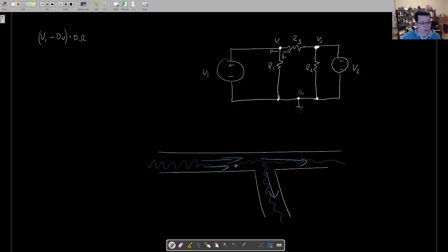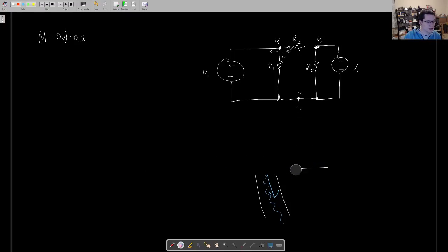And at the same time, everything you've put into your pipe must come out of your pipe at some point. If you just keep pushing water in, eventually part of your pipe's going to explode and let the water out. Unfortunate but true. Electrons in a circuit are no different. If you put them into a node, they have to come out of the node. So everything that goes in must come out. If you're net non-zero, something is wrong probably with your calculations.